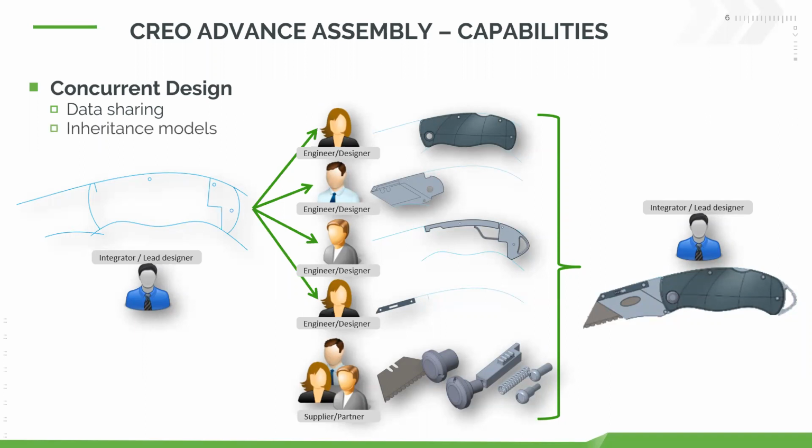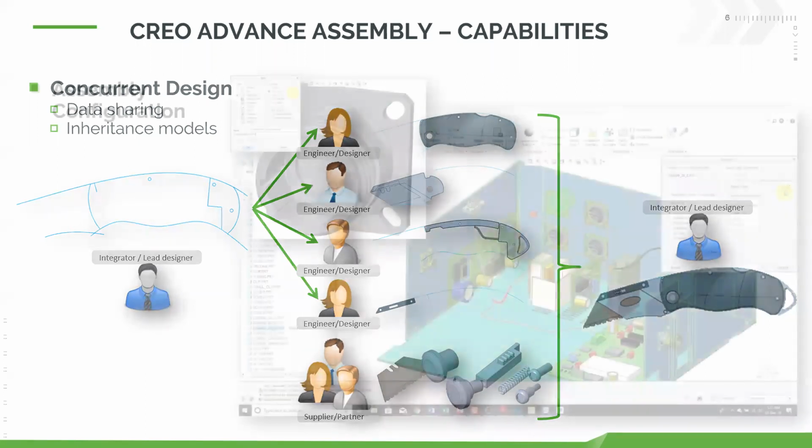This also uses what we call inheritance models. This is controlling whenever you make changes to certain parts or subassemblies at the top, whether or not those changes then get propagated down the line, or vice versa. If you make a change to this inheritance model that you have defined down the line, that doesn't affect anything from the top down. So this is really an essential part of what we do for things like assembly models, when we work with analysis models, whenever you're even doing manufacturing models. Sometimes you have to do things like shrinkage for manufacturing. These are all very useful for using inheritance models.